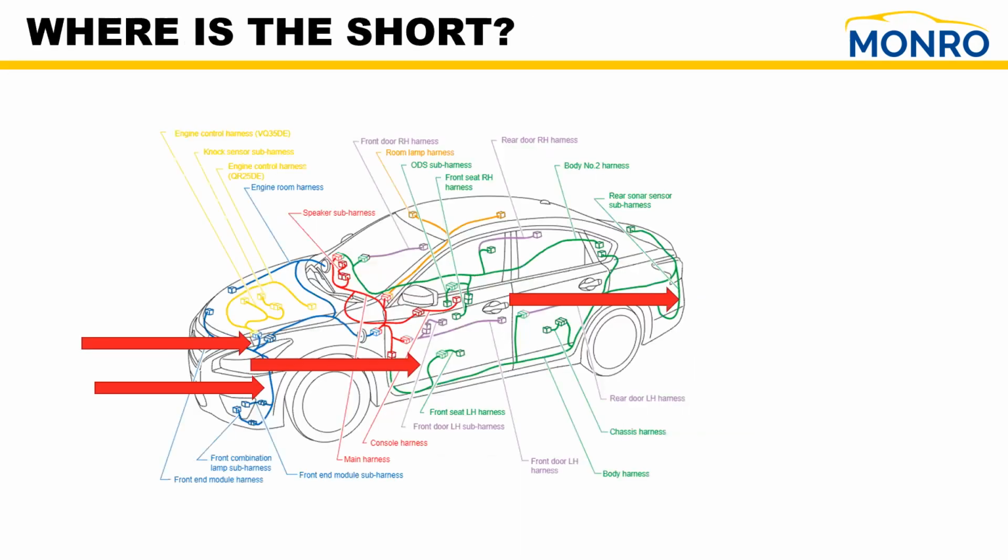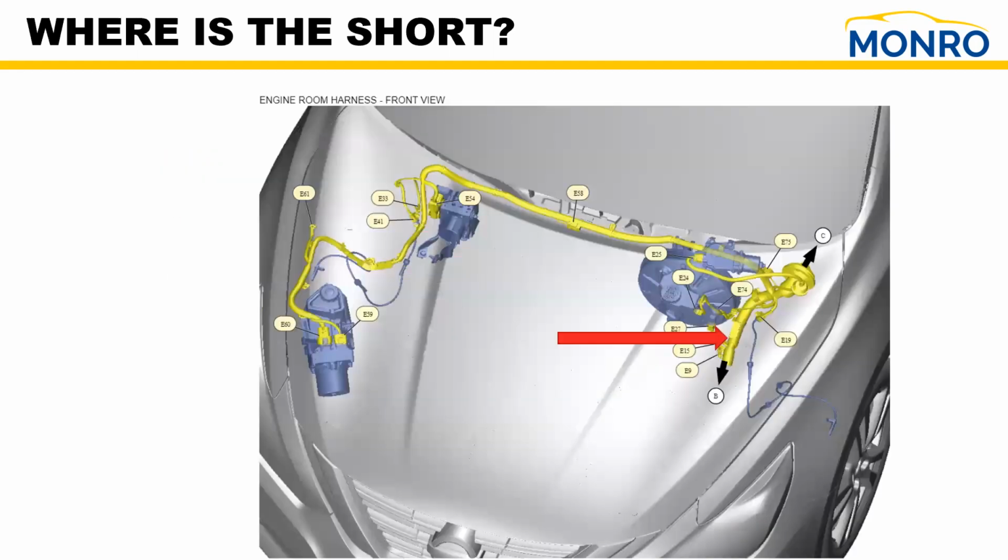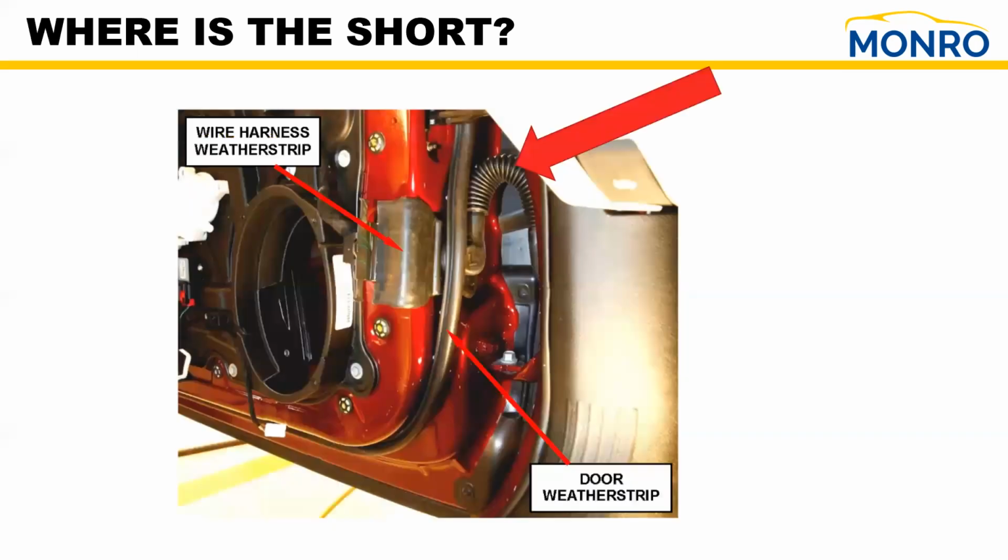In some cases, the hood opening and closing. A bad motor mount causing the engine to rock, stressing the wiring harness. Or even when a guest is pulling in maybe a little bit too far across a curb stop. Remember, any place that there's motion, that's the first place I'm going to begin to look.